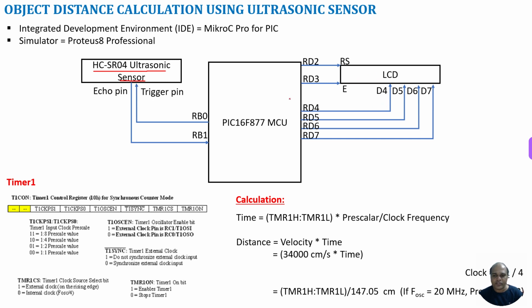So in order for us to use the timer 1 module, I am going to configure this timer 1 module using a register called the T1CON register. T1CON is the timer 1 control register. It's an 8-bit register, so here we need to do the configuration part. I take these 2 bits, T1CKPS1 and T1CKPS0, which are used for setting the prescale value. What is a prescaler? It decides how fast, or when, I should increment the timer registers. That is decided by these 2 bits.